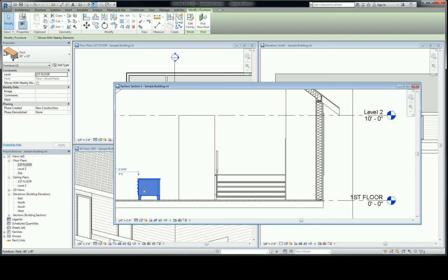I don't see a reason that you would be able to create a wall that's smarter than the walls that are in there, unless it's a specialty product, in which case it would need to be a family, not a system family. What about a custom staircase? In that instance, would you try doing it as a component? Oh, yeah. Like a spiral staircase or something? Well, Revit does some simple stairs. Stairs are the worst part of Revit. For some reason they haven't been able to figure out how to make it intuitive or easy to work with by any measure of the word easy.